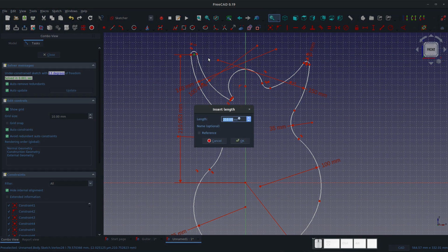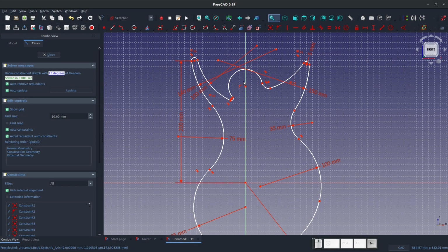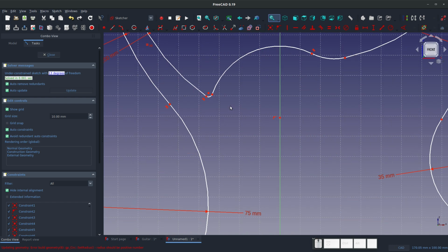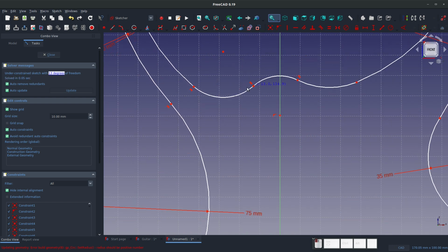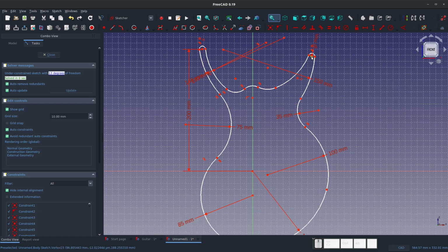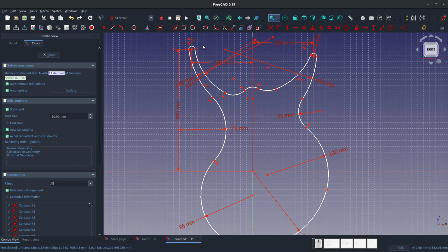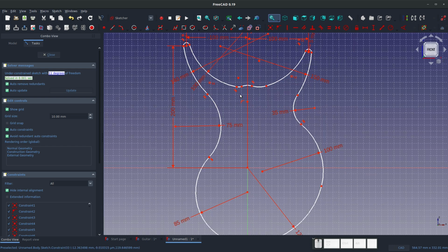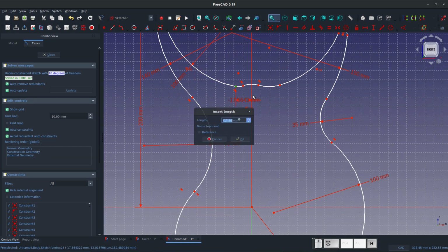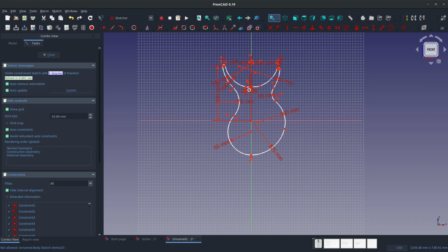I'll take this as a vertical dimension with Shift V, right? Click on that point, Shift V to 200. Bring that guy down, horizontal to 100. Another horizontal, negative 100. And that's, of course, Shift H to get that, but you can already see that on the keyboard monitor. That's looking kind of guitar-like there. Go with negative 20. 10 is fine.